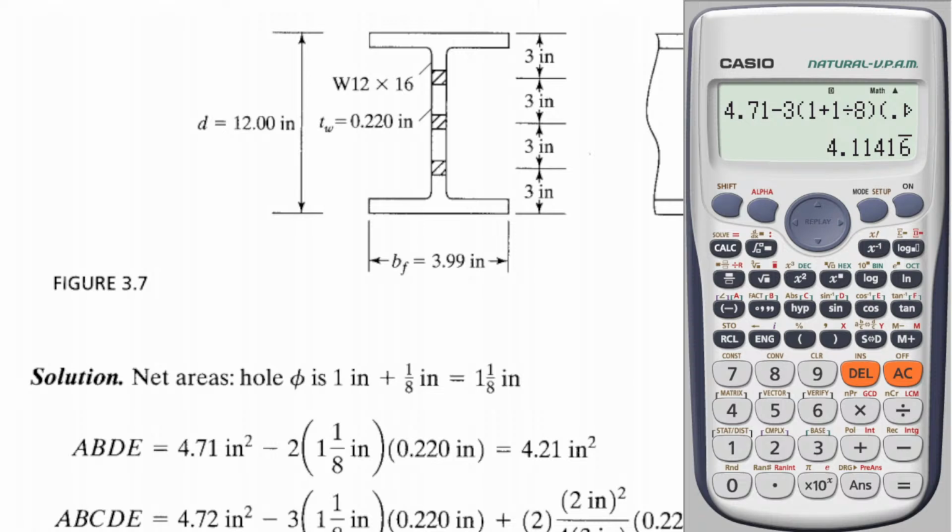Any question with regards to this? Please remember S squared over 4G. That is our formula for staggered holes.